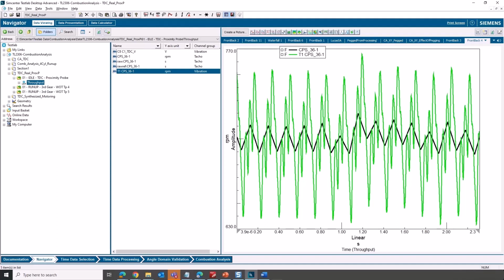Yes, correct, Pete. In this particular case, we are using the proximity probe sensor signal for the top dead center determination. We see that there is this proximity probe, and then there is the 1 pulse per rev signal, and then we have the multi-pulses per rev. And these here, the raw and the raw reference, correspond to what are called tacho moments. They are the moments in time at which the pulse crossing occurred, and they are captured also. Those will have the information about exactly when the pulse crossing happened, and so we will use that information for the TDC determination.